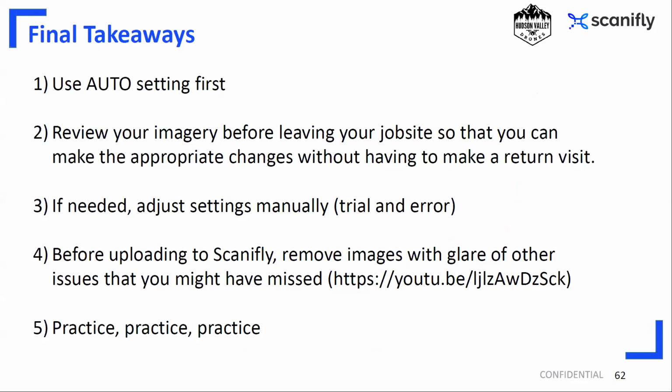After reviewing your images, make the adjustments if you need to, and check your deliverables again. And if you have to fly it again, do that. It's a lot better to fly a mission 2 or 3 times, or redo it when you're on site, as opposed to leaving and going back to the office and getting ready to upload everything, and then realizing that half of your imagery isn't usable, and then you have to go back out again. It's just not a good look for efficiency, and it's not a good look to your customer.